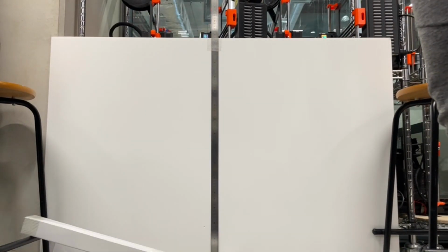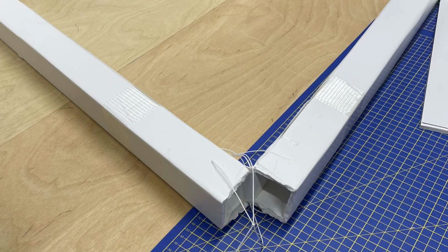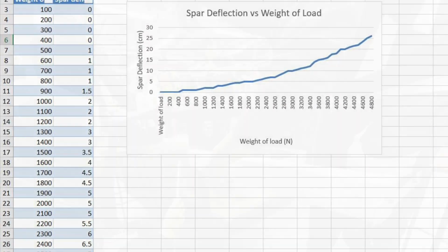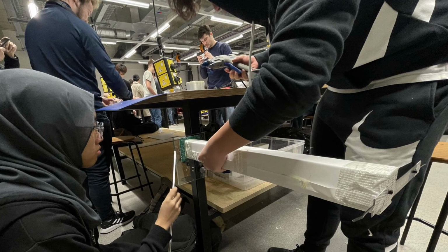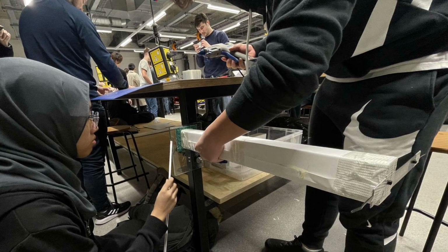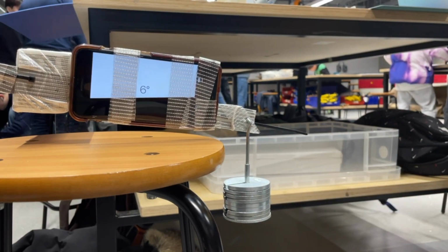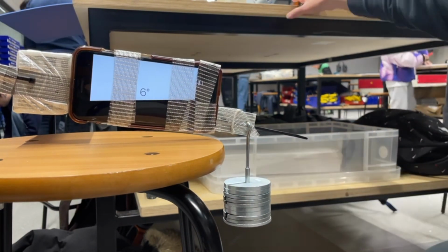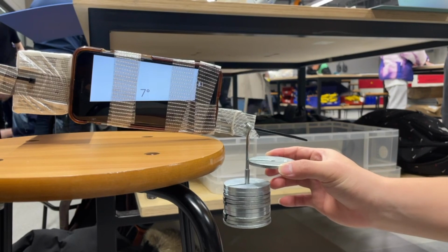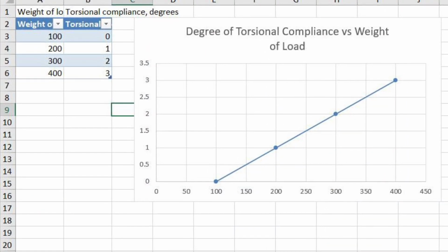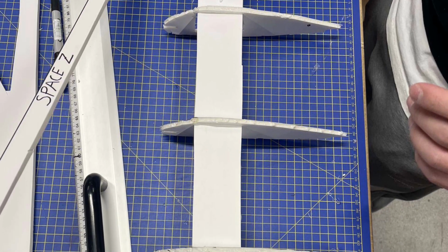Area moment is higher when the material is further from the neutral axis, and therefore meaning less deflection and an increased bending strength. As a result, we settled on an I-beam cross-section, as it had a much higher second moment of area for the amount of material used, which keeps the weight low, but was strong enough to match the requirements. To conclude, we've learnt a great deal about design and ended up with a finished project.